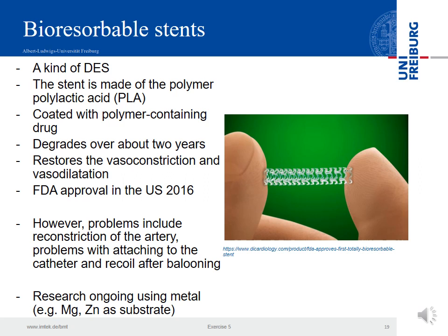And if you take, for example, magnesium and zinc, that are also trace elements in the human body, you can make a bi-metal layer stent that gets first dissolved due to the different electrochemical potentials of the two materials in contact, and afterwards, when one is left over, then the body takes over its job and dissolves the other one. Dissolution goes slowly. That means the amount of metals is still at the level of trace metals, and no toxicity is around.